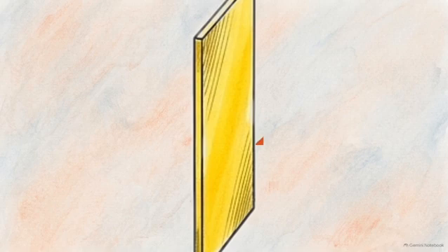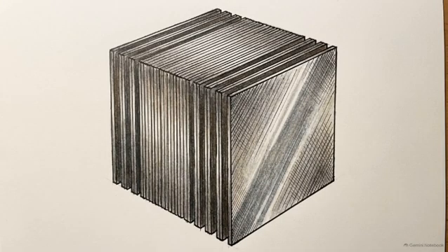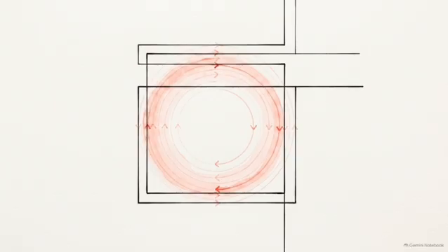Restricting the physical radius of these loops drastically increases the electrical resistance they face. This forces the current magnitude to drop, preventing massive heat buildup. Lamination is an elegant geometric hack. It allows the metal block to safely carry the vital magnetic flux it needs for grid power, while mechanically strangling the parasitic currents that would otherwise damage the system.